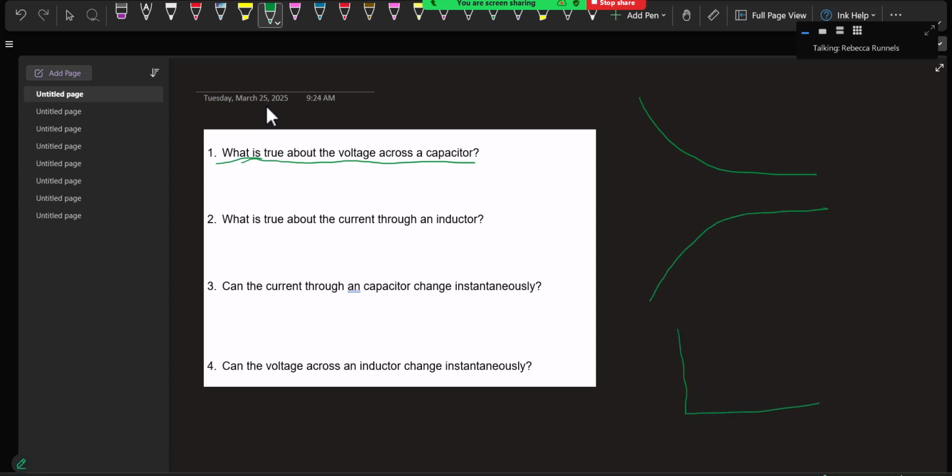But you said like if it's connected to a battery, and then it'll have the same voltage as the battery. So let's say it's right here, and it has 9 volts. And then you throw some switch and the circuit changes. Can it be at 9 volts and then suddenly be at 3 volts? No, it can't do that. So it can't change instantaneously. And by not changing instantaneously, I don't mean this. It can have smooth change, but it can't have a jump.